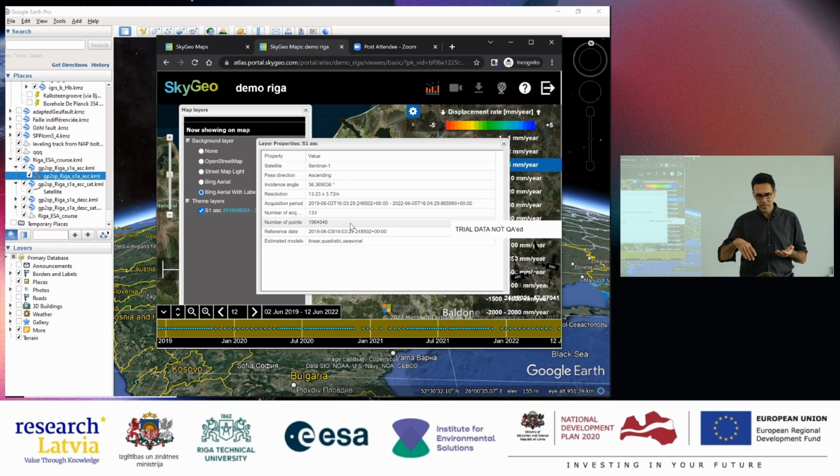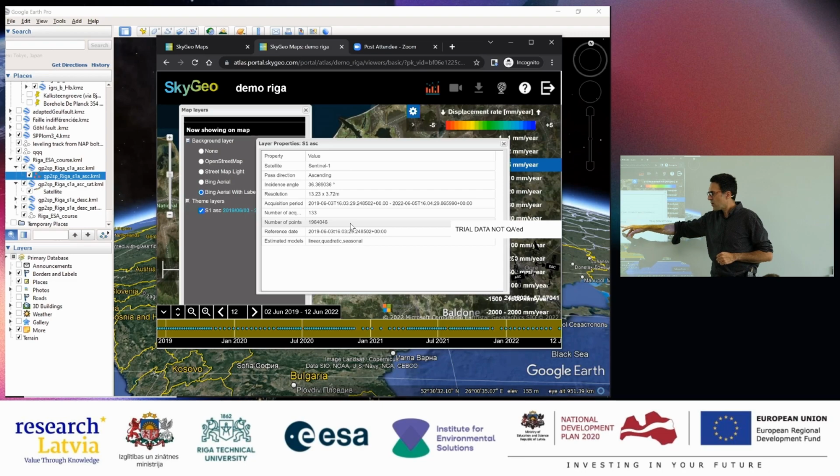So for example, a metal mass will go up in the summer, so it will get closer to the satellite, but a peat soil will dry out in the summer, so it will go down, so it will be further away from the satellite. So if you look at that as a sinusoid, the maximum and minima will be shifted, depending on which point you're looking at. But this means that we are using these parameters, so these are basically like 4 or 5 parameters, plus the elevation as the unknowns in our data set.